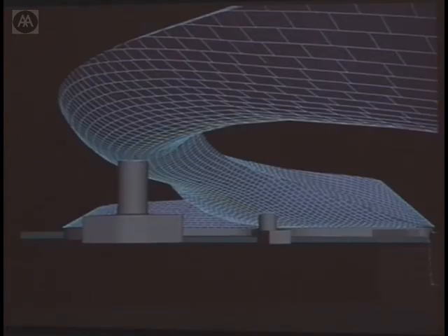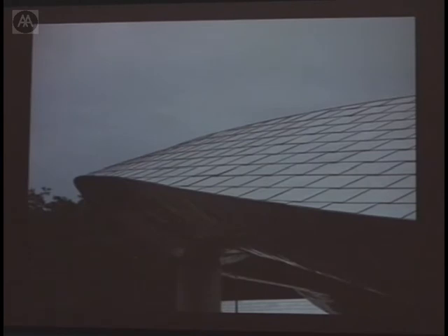And I got a question trying to find a sort of level of panel commonality. So at some point there's a straight line happening here, which is basically the Euclidean bisector of an arc, meaning that you're not actually calculating curve length along the curve, but actually along 2 points along a curve that are defined by a straight line. And so this thing creeps around and lays out these panels. You can then wrap them back onto the surface like that, and this is what you get. And you get this kind of nice sort of fish scale texture.